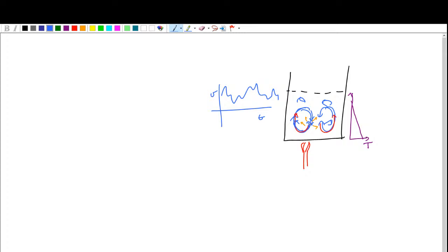In gases, it is comparable to what is called the mean free path, which is about 0.1 microns, whereas this motion is taking place over a distance comparable to centimeters. And because of that, this is referred to as a fluid velocity fluctuation rather than a molecular velocity fluctuation.